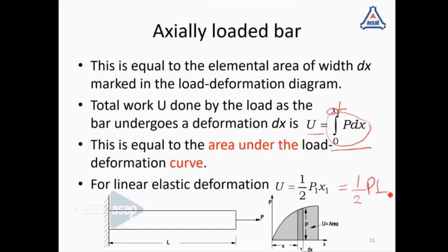So for linear elastic deformation, this curve will be a straight line. This is P and this is L. So the area of a triangle is there, and that is given by half of P into L. So this is how we evaluate the strain energy of deformation.